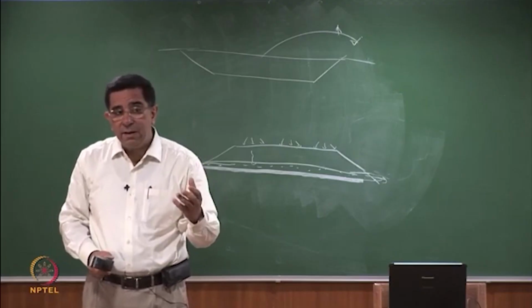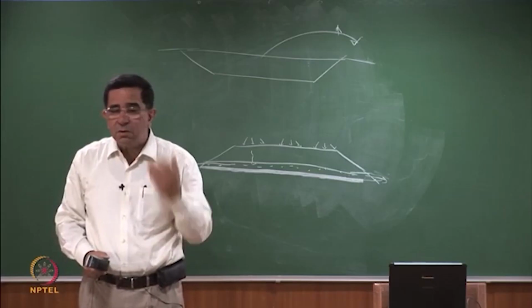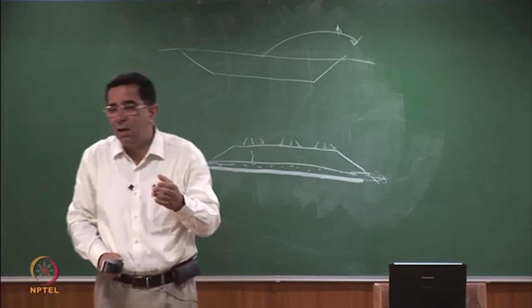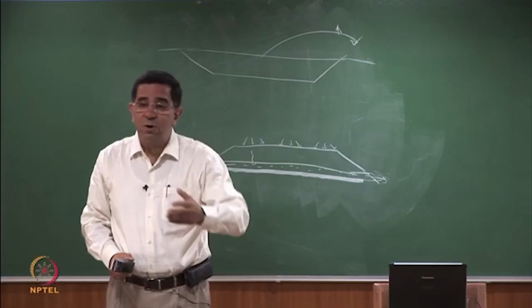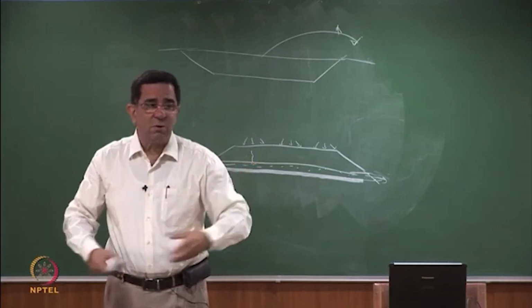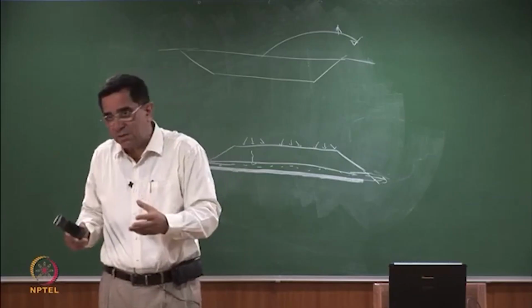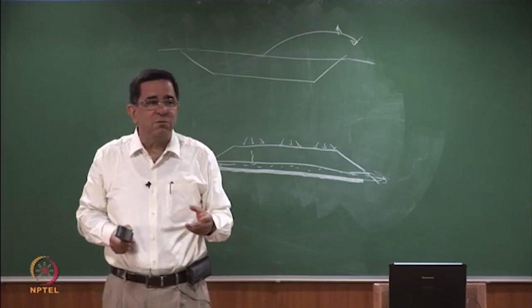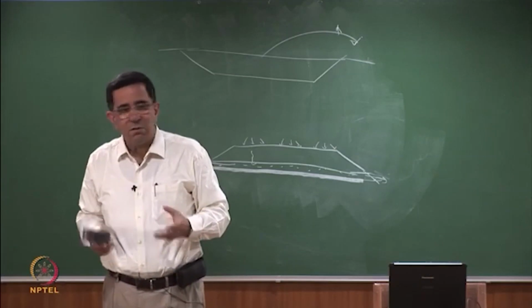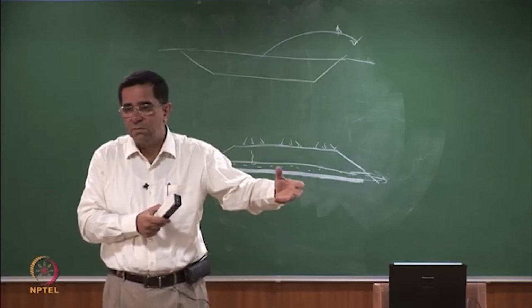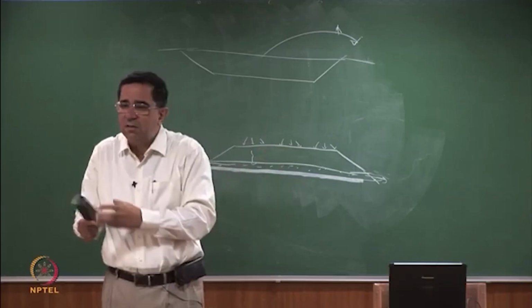If you are in a great hurry, maybe you would like to fractionate your soil. Why? Because there is a chance that the contaminants are only in the fine grained. So, you do sieving, take out your coarse grained soil. Coarse grained soil will settle very fast, it will be available for you very fast. The fine grained soil may require some treatment. So, suppose 70% of the material is coarse grained soil, so half your problem is solved, because coarse grained soil will come over the sieve. You can wash it very quickly, it settles very quickly. The fine grained soil is something that you have to tackle.